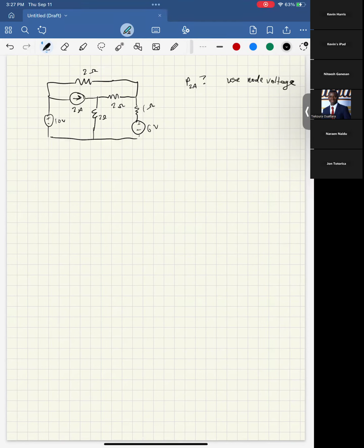So our ground, generally, unless your teacher's being really mean, which I don't think Professor Dunning is, it's usually a safe bet to just put it at the bottom of the circuit. For this specific case, as I was saying, you define it to make your math the easiest, so you want to define it where as many components as possible are touching.